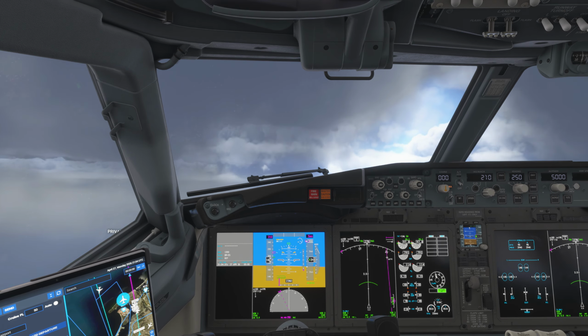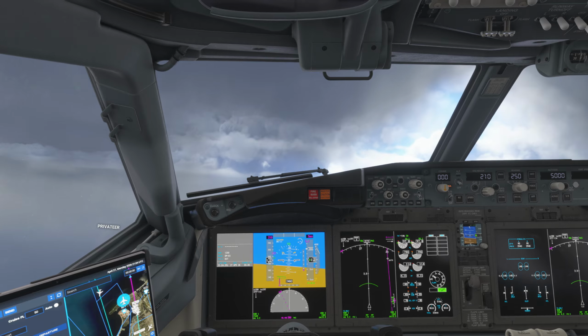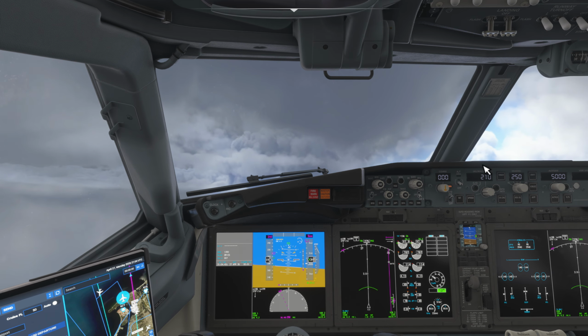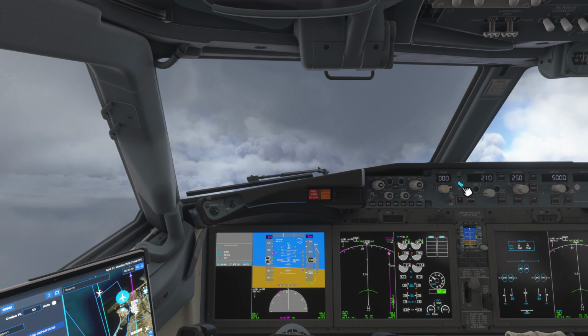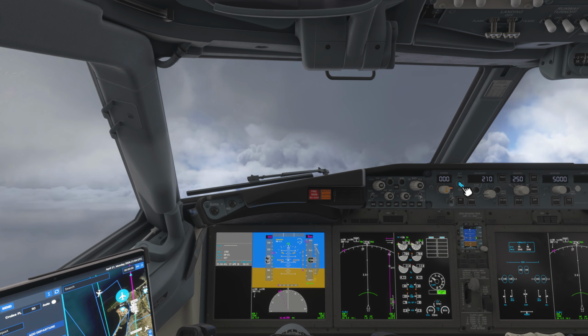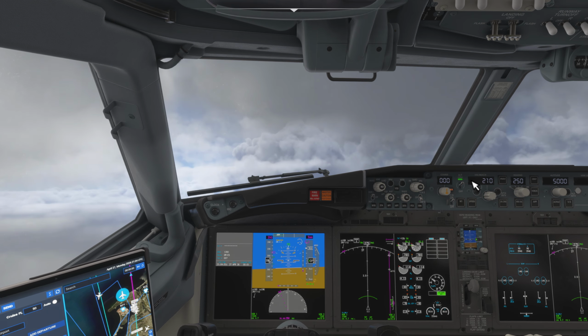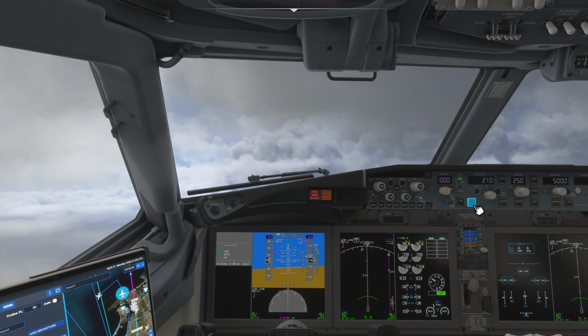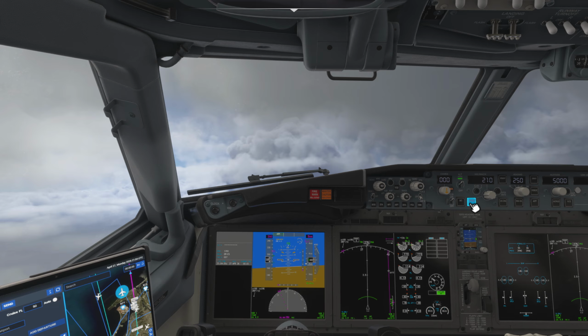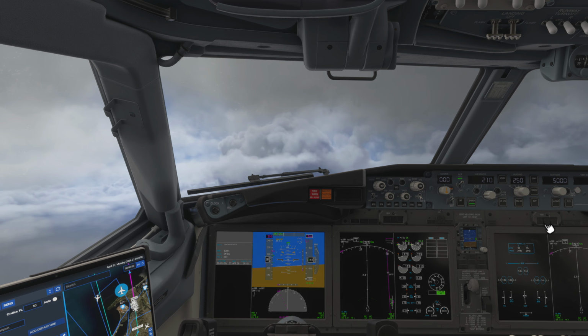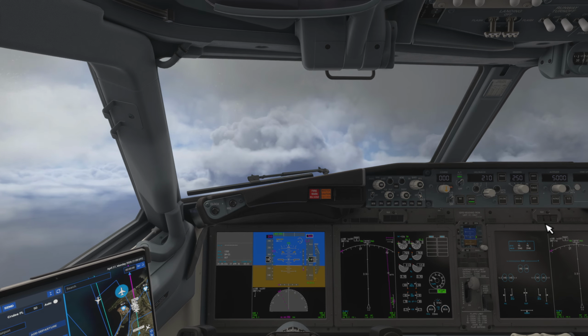Alright, I'm going to go to 10% on the flaps there. Start setting up the autopilot and get her kicked in. So, again, let's activate our speed indicator by clicking that button up and pressing the speed button. That tells the airplane that we want to do 210 knots.